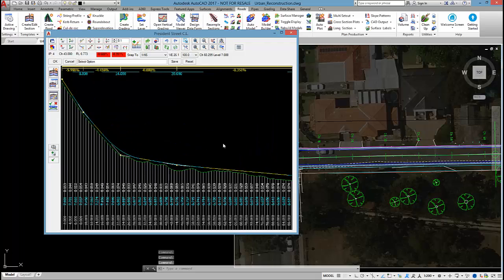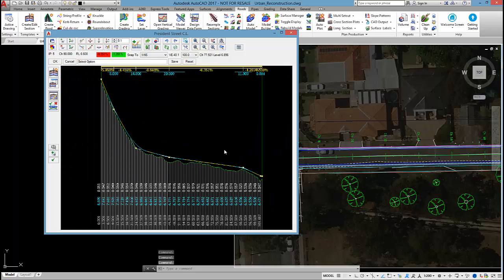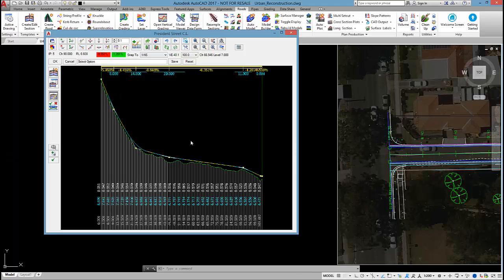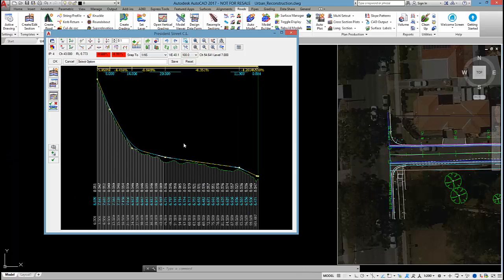A few areas around the vertical curve are a little bit off, but what this gives me is a good starting point for the design. Now at the start and ends, we will be transitioning into the main roads here, but we'll set that up when we create road objects out of these edge strings. In fact, the software will transition for us automatically on that.